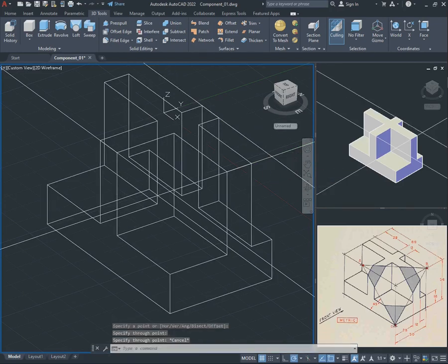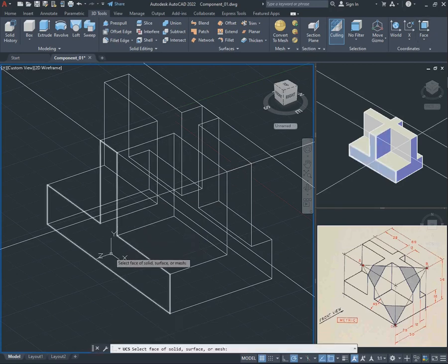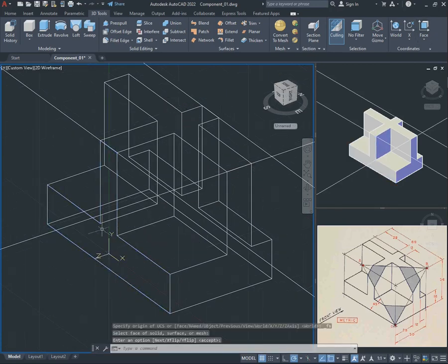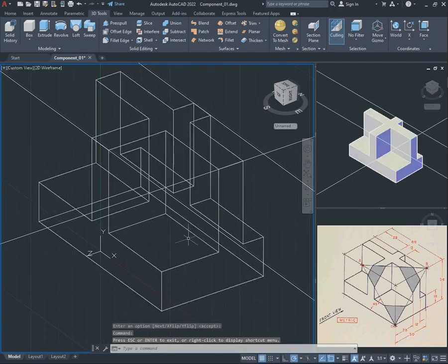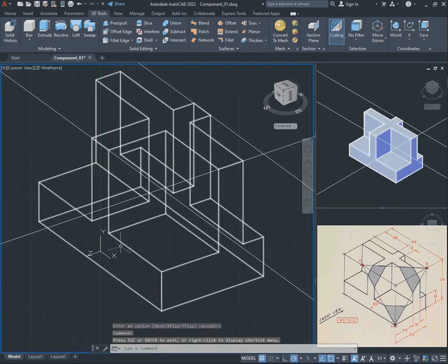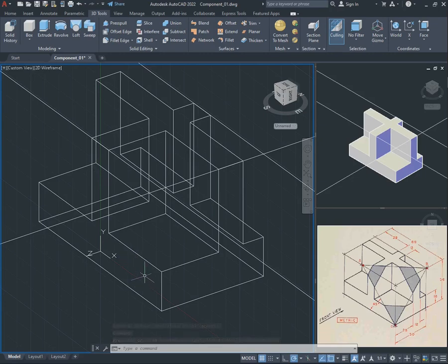I'm going to change again the coordinate to this side of the object. And then here in the illustration of the component, we have a degree, which is 45. In this Cartesian, we have the first quadrant. So here we need to do a simple mathematical computation. We're going to use the cal command.